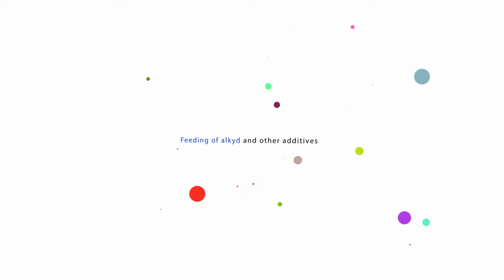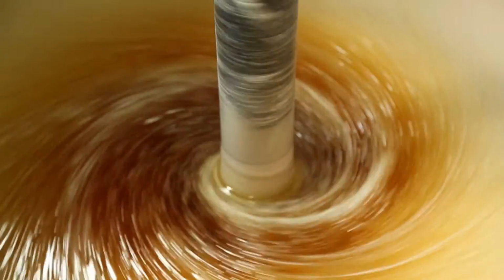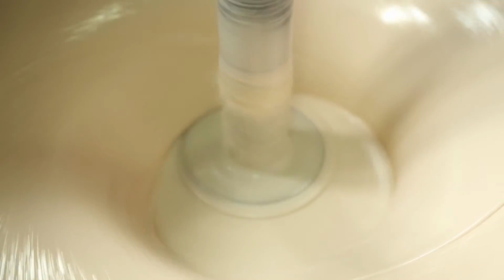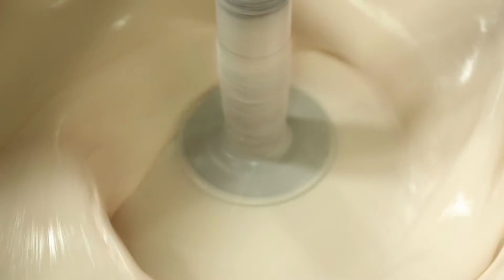Feeding of alkyd and other additives. After completing the dispersion and grinding stage, alkyd resin is added to the mix and mixed for 5 to 10 minutes. Later, final additives such as drying agent, solvents, etc. are added and then mixed for 5 to 10 minutes to complete the production.